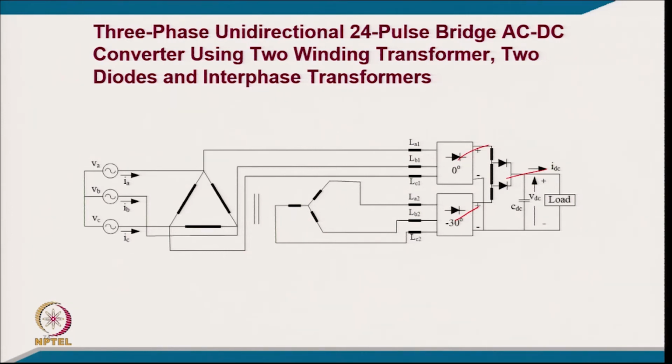One is the phase staggering or phase shift, another is the multi-phase, that is, we converted to multi-phases, and the third concept is ripple injection or pulse multiplication, as we call it, or pulse doubling with the diode. With this we can increase the number of ripple injections and increase the number of pulses, not necessarily just double; 3 times, 4 times also people have practically realized, even in research laboratories.